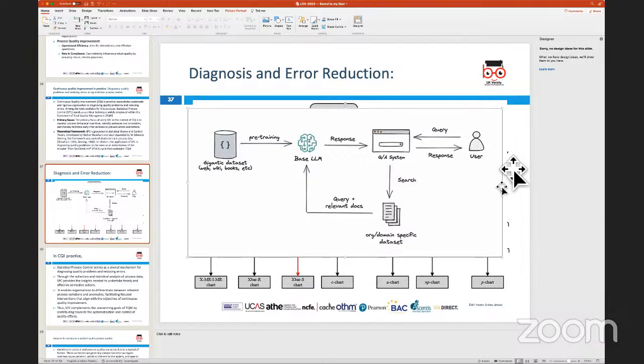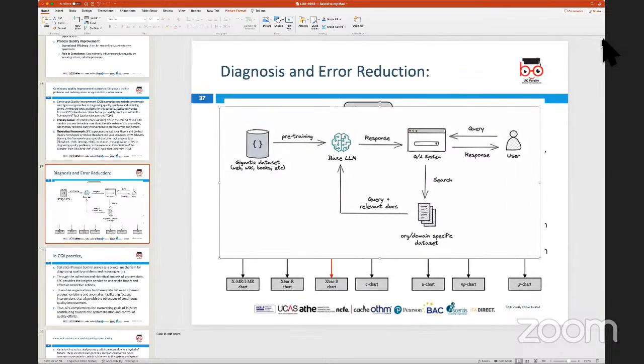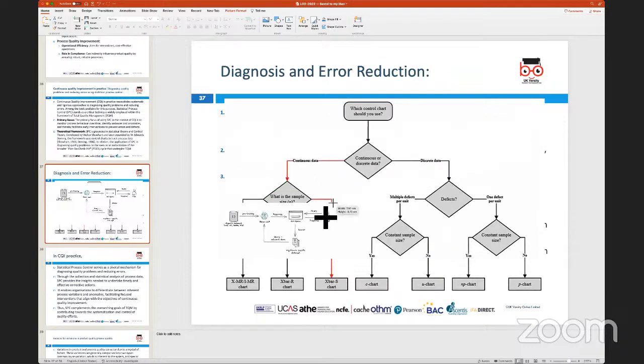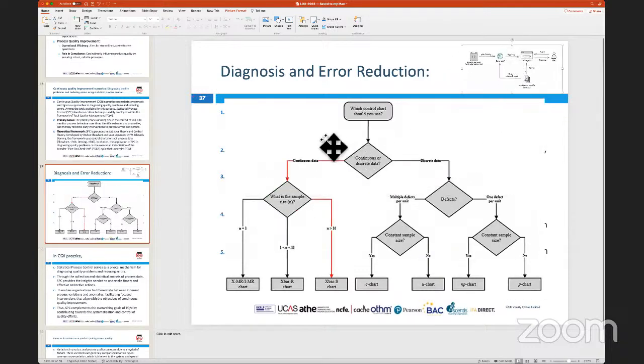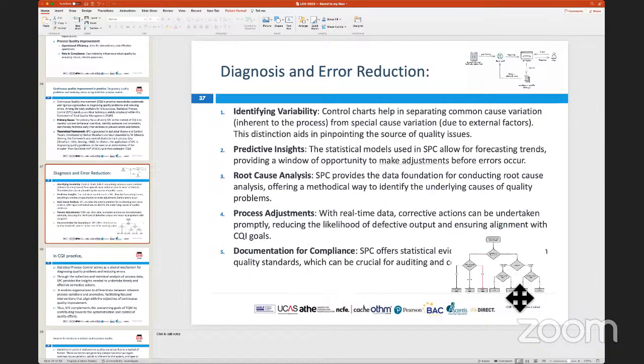So these are data charts, or control charts essentially, which are established to visually depict the flow of how the process is going to run. Using a lot of data collected over a period of time, they would be drawn up and used as benchmarks to reduce defects or diagnose any sort of errors that might occur in production or on the production line for a particular product.